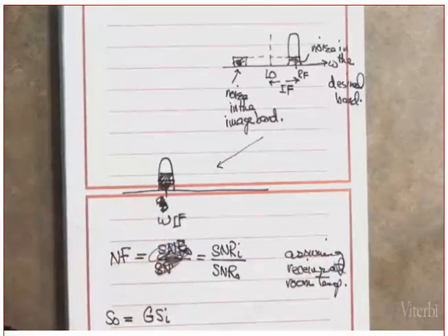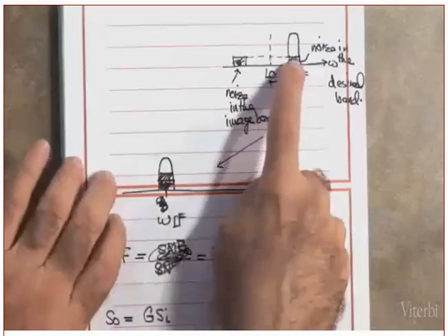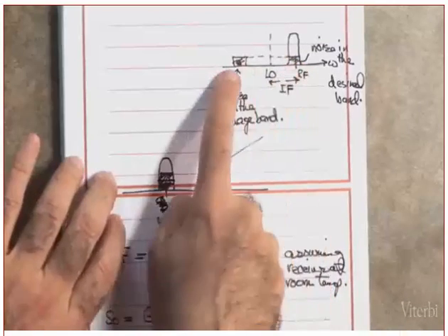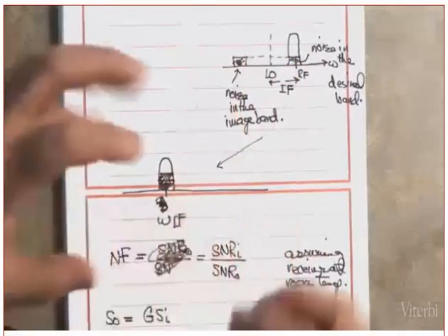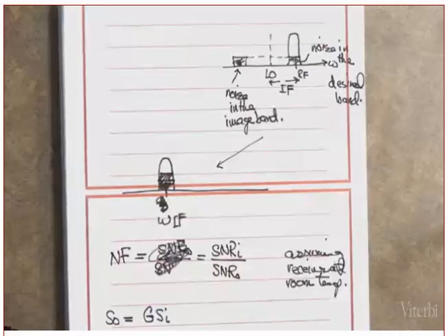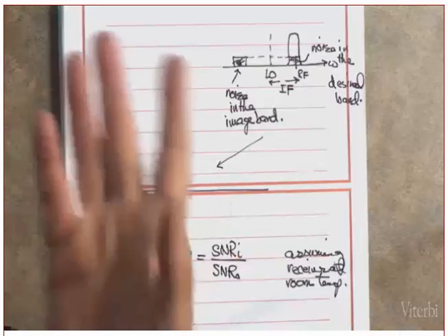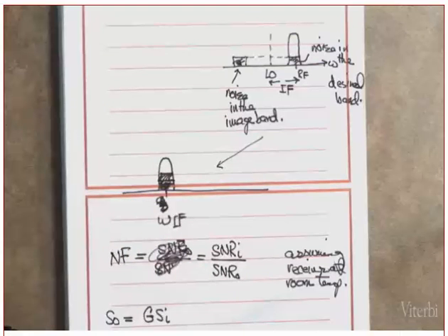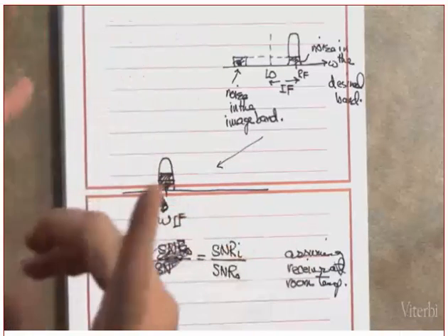By the way, I don't know what the model of the noise is. If you assume that the noise generated by the mixer is also white, then it means that some of it will be in the RF, and some of it will be in the image, because it's covering the entire band. It depends on how you model the internal noise generated by the mixer. Where is this coming from? If you are using a transistor, which we will show in just a second, it will be generated through the ID.